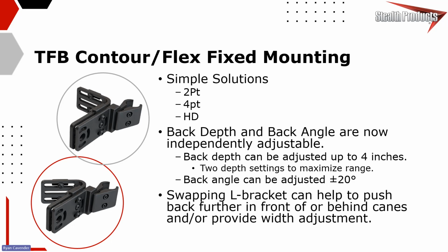So basically the 2 screws here that sit a little bit proud of everything, you loosen those. You can adjust the overall angle of the hardware. There's 2 here that are kind of hidden away. You loosen those 2, and that's your depth, and angle stays fixed.